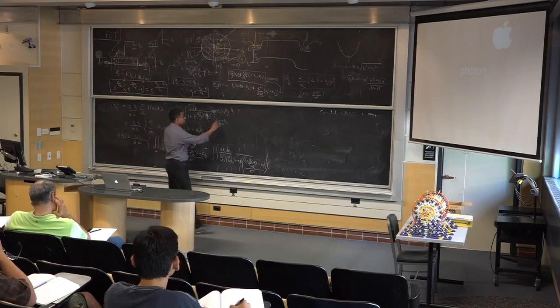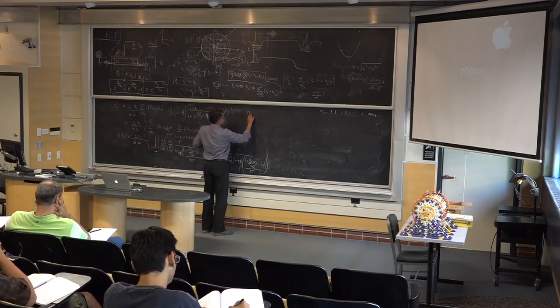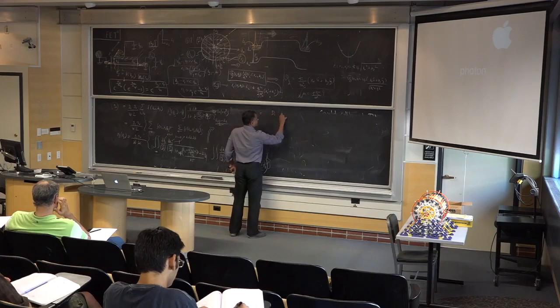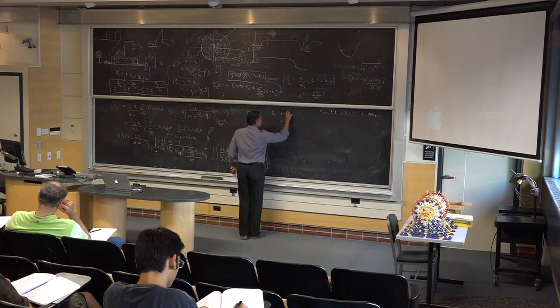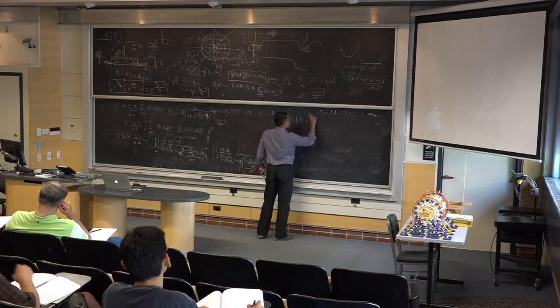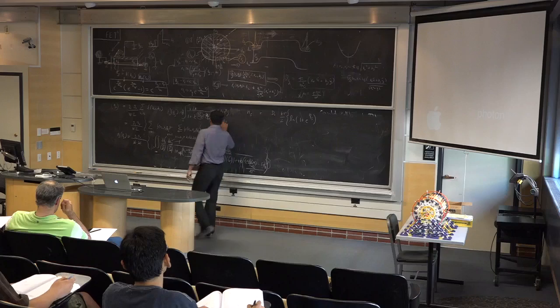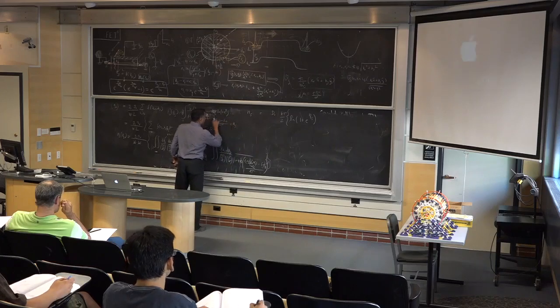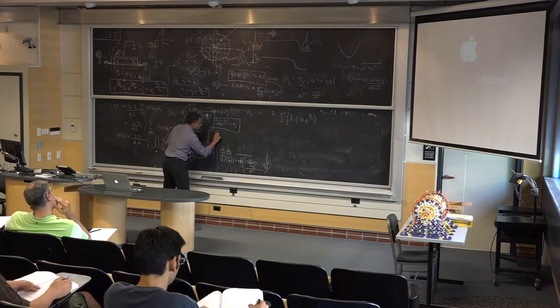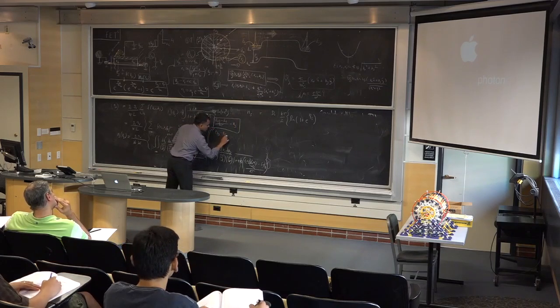So let me write down the full relation then. After you solve that integral, what you'll get is D naught kT over 2 natural log of 1 plus e to the power eta sub source. What is eta sub source? It is this. And similarly, eta sub drain will be the Fermi level of the drain minus EC over kT.